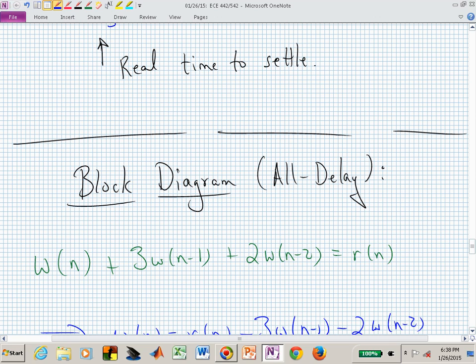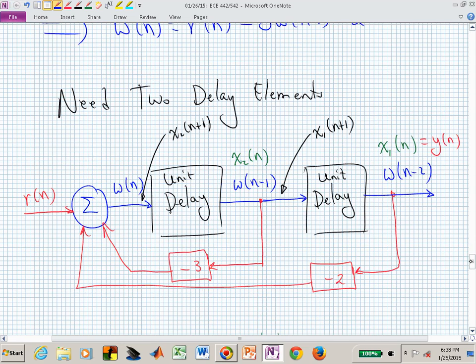You need to start becoming comfortable with the green equation, the block diagram, and the state space representation. The state space representation you can now almost visualize as an interconnected block diagram with these blocks being delays and having particular weighting coefficients and summing junctions.